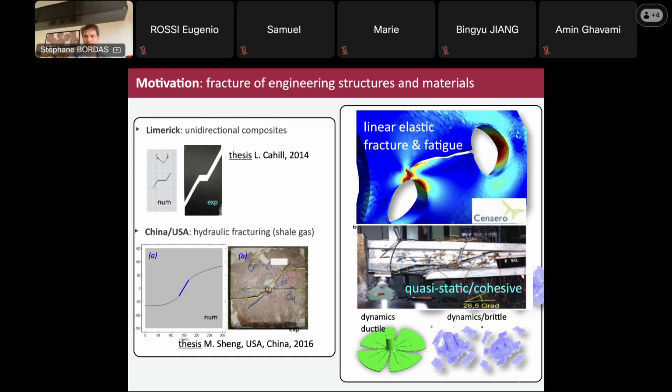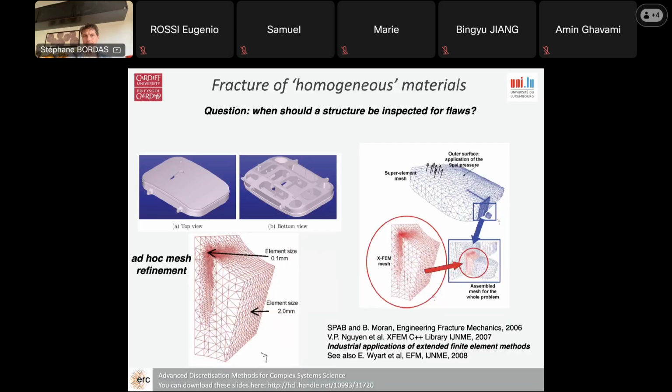So at the left, you have a ductile fracture, meaning that the material slowly deforms and eventually breaks, but progressively. You see the deformations are huge. On the right, what you see is that the material is brittle or quasi-brittle at least, meaning that you end up with loads of fragments, but these fragments are not continuous anymore with the original structure. So that is why it is very useful to have an idea how you deal with cases where the finite element method is not able to do very well.